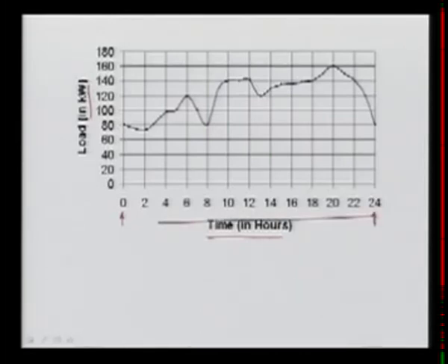You can see the variation keeps changing, and sometimes the peak may even occur in the evening; it depends upon what type of load you are using. For example, for industry or a commercial organization, your peak will always occur in office hours. But if the substation is feeding domestic load, the peak normally comes in the evening, because all the lighting, fans, TV, and refrigerator are on.